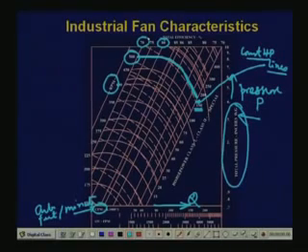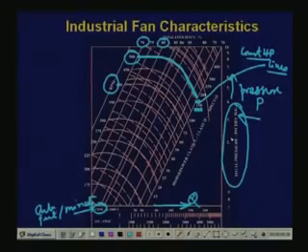So this curve shows the pressure-flow characteristics when the fan is operated at various speeds, with something constant, either the speed or the power, so that you can conveniently find operating points. In fact, we will use this curve later to compute the energy savings. Having understood this, let us move on, and we will come back to this curve in a while.